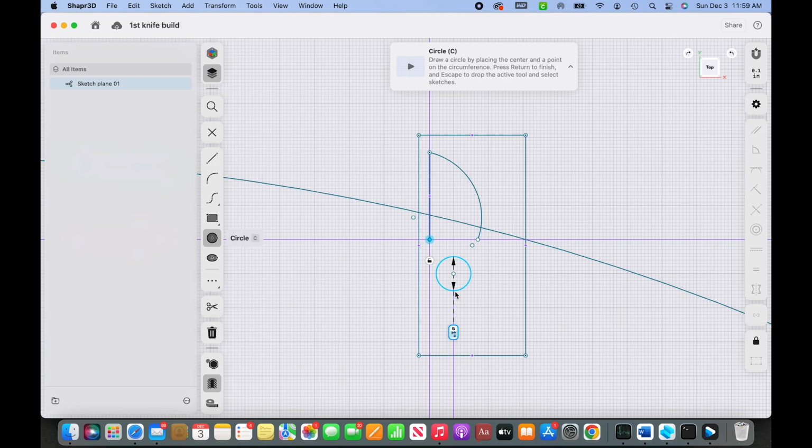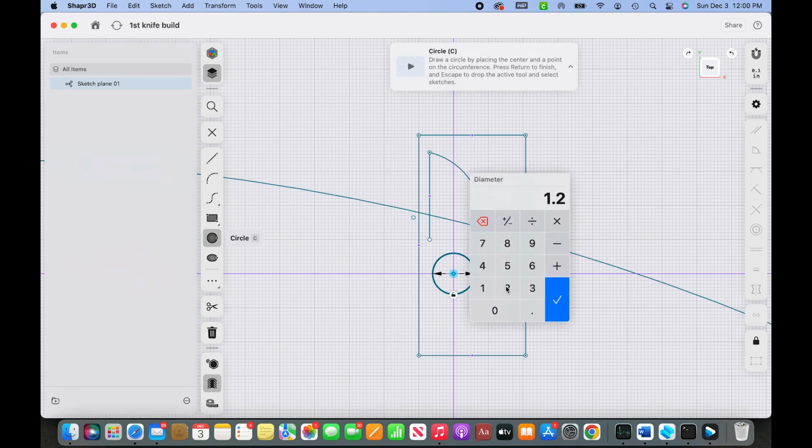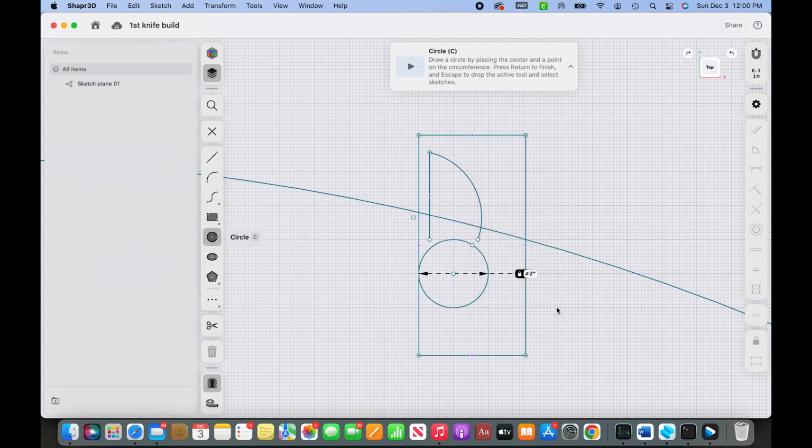Just a small side note, when I was trying to find something to give me the diameter of my finger for finger holes, I used a key ring. Easier to use a round object when you're freehand drawing a circle. And when I held the key ring up to the screen, the diameter was off. I finally figured out I could use my digital caliper and measure my finger and type the dimensions in the circle diameter, and it works much better.